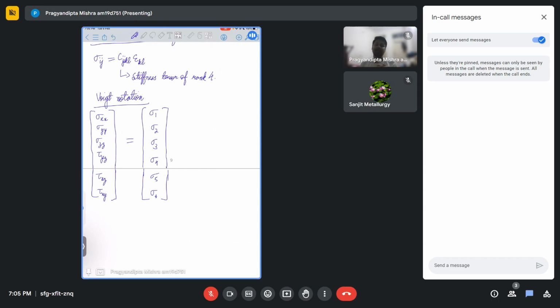What has happened now is, because we are able to reduce the rank from 2 to 1 for stresses and strain, the rank of the stiffness matrix Cijkl also reduces from 4 to 2, right? So it will become something like sigma i equals Cij times epsilon j. So your entire coordinates are now manageable because it's in a two coordinate system. Understand that this sigma 1, sigma 2, sigma 3, or epsilon 1, epsilon 2, epsilon 3, all those values are not principal stresses. Do not confuse these with principal stresses. They are just notations given to stresses so that you can do calculations quicker and faster.